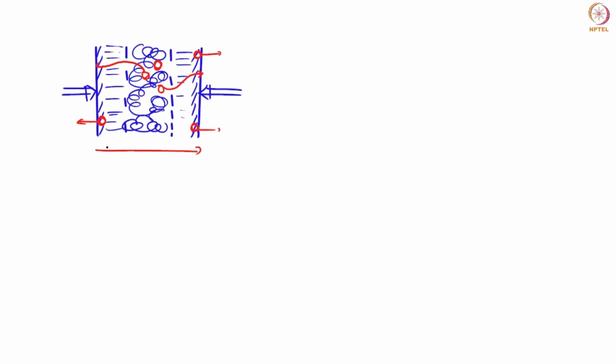There will also be a thermal conductivity difference, because this material is already carbon at a given temperature, while this material still contains a lot of tars and bubbles. So of course there is going to be a thermal conductivity difference. The temperature reaching the core of this structure may not be the same as on the surface. Due to all of these things, often the core remains, let's say, uncooked, while the surface gets cooked. Okay, so this is the problem. What do you do if you are given any polymer? Whatever I have asked in the question, what you can actually make is something very simple. You can make a wedge-like structure.